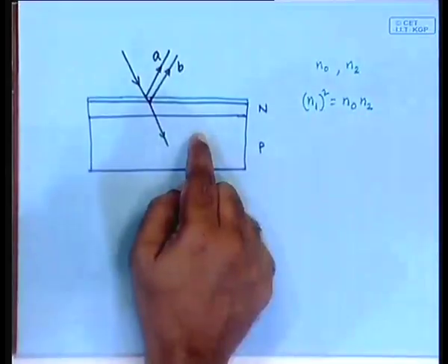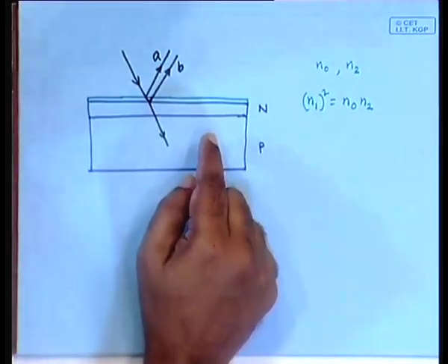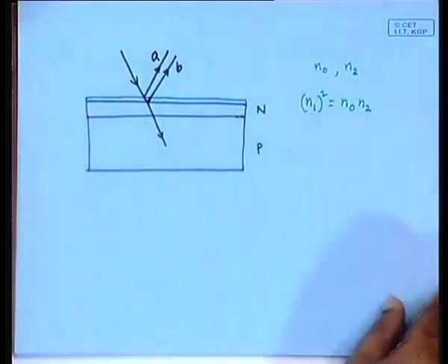So, this is how the anti-reflective coatings are used in order to increase the efficiency, and this is another thing that degrades. If you look at old photovoltaic cells, you see the coloring is different than the new ones. The new ones have a different type of texture coloring, that is mainly contributed not by the silicon, but by the anti-reflective coating, and that is another thing that goes down, degrades over the years as time progresses. Okay, so you have understood the idea of the anti-reflective coating.